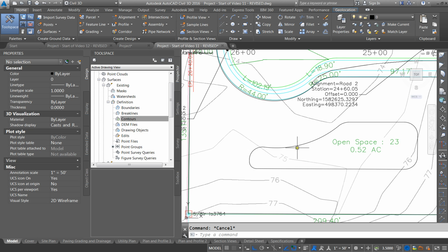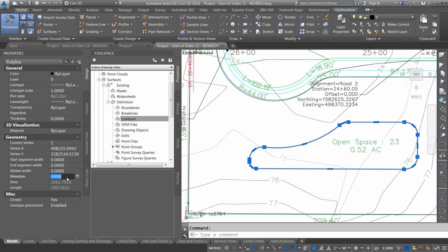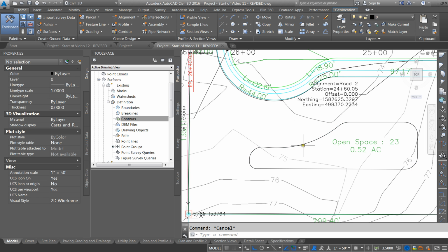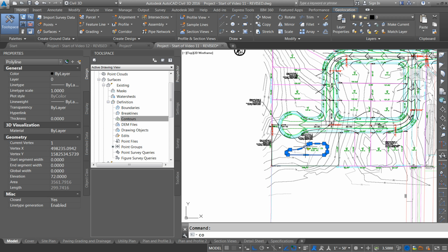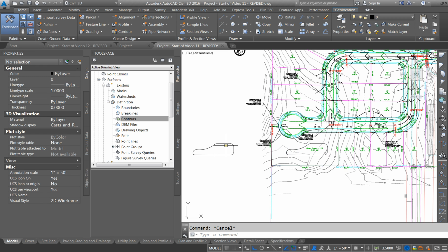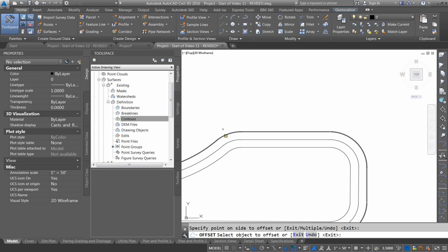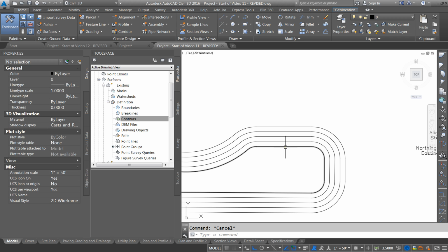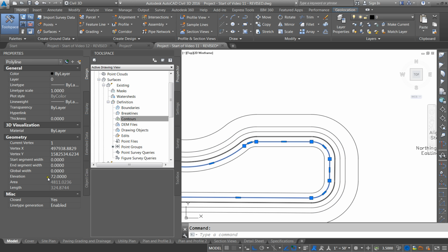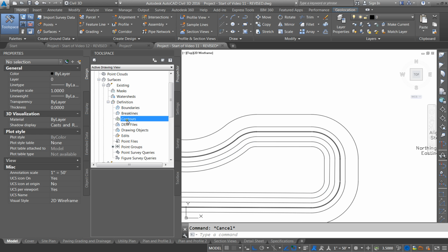So now what I've got is I've got my control, and I can put an elevation of 72. It's just a regular polyline. If I wanted, I could just take this, and I'm going to move this over. I'm going to copy this over here. I could now just take this and offset it 4 feet. 2, 3, 4. 4 foot depth, 4 to 1 slopes, and then offset 10. And I can change these elevations to match what it needs to be and create a surface, by saying that these are contours.